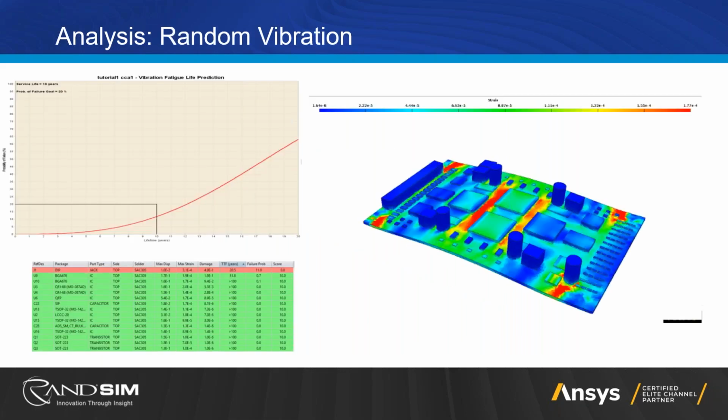And so the random vibration, you can see here when we run it through the random vibration profile, you get another pretty cool looking three-dimensional representation of how your board is impacted by that random vibration, where the strain is maximized, and you can kind of see a couple spots. You have your mounting points, but then you also have it along both edges of where these two BGAs are soldered down. And so, we get a passing predicted life value.